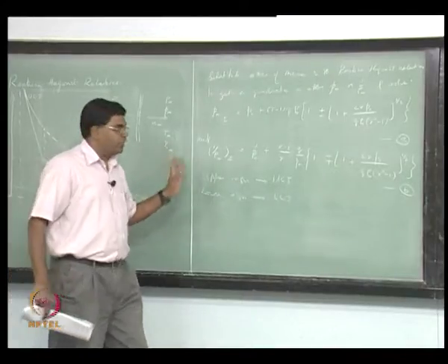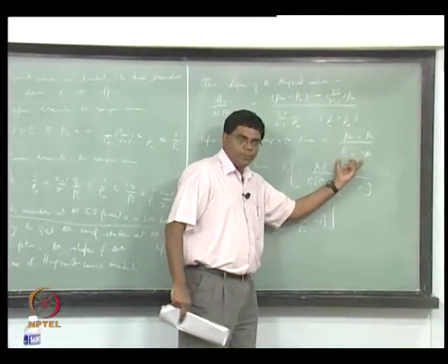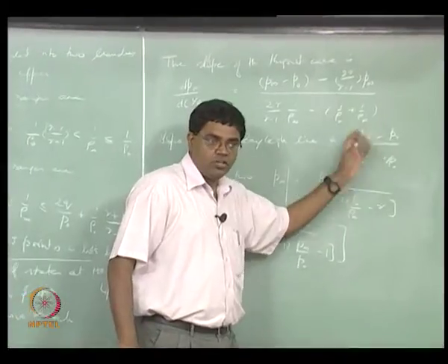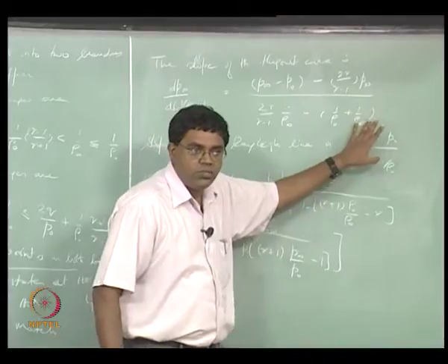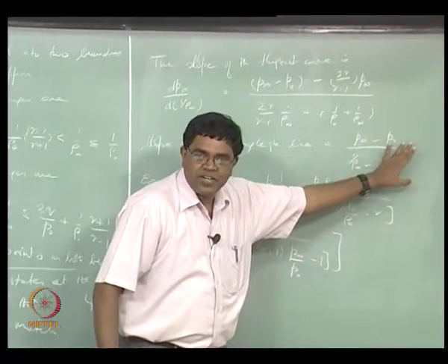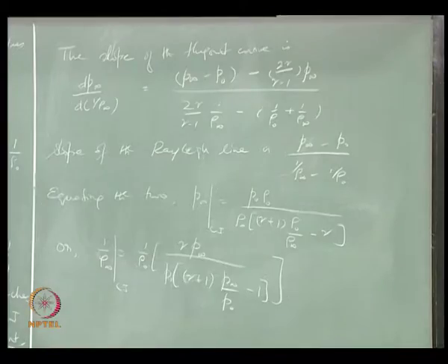So we have really not used the Rayleigh line information except to note that that is the slope, but that's just the slope written in terms of thermodynamic variables. We have not brought in the fact that this is equal to minus m dot squared, right. So that's what we want to do now. We want to notice that the slope that we had used for the Rayleigh line is actually equal to minus m dot squared, and then get to the flow information.